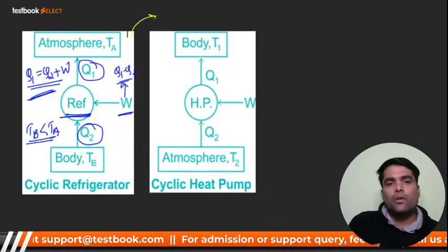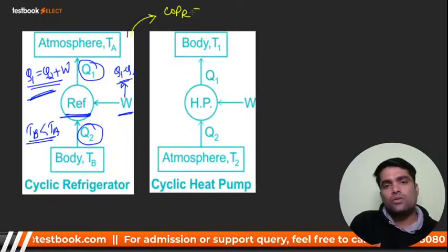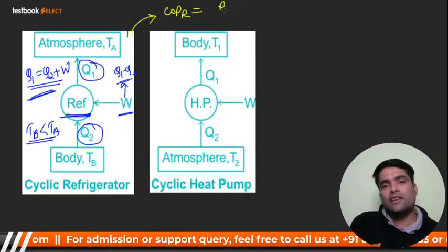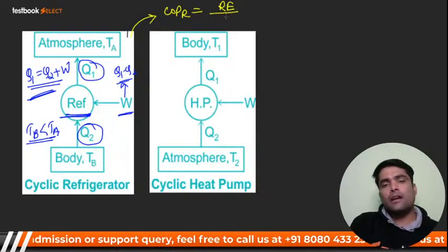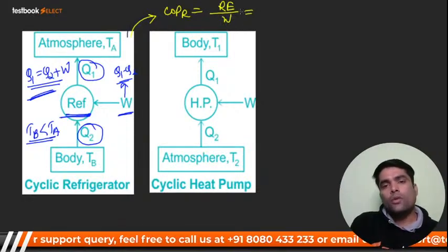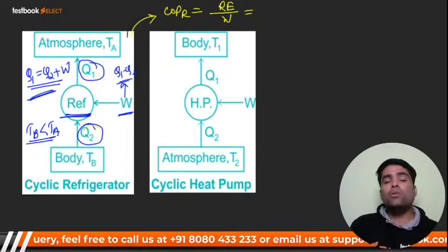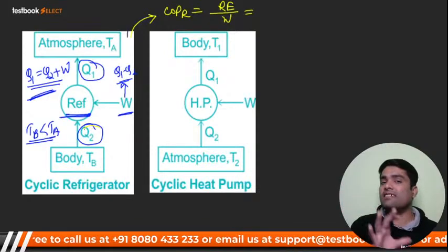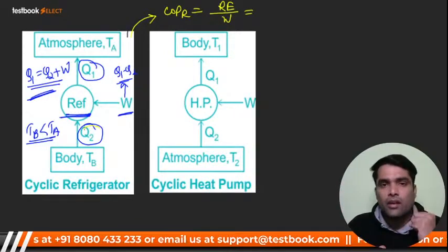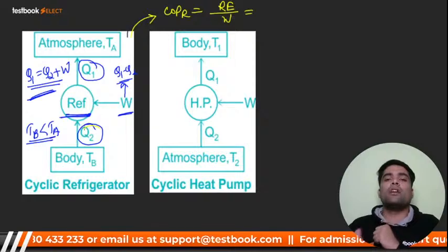What is COP for refrigerator? Right. So COP of refrigerator, that is desired effect, that is refrigeration effect, divided by W. So what is the refrigeration effect over here? The amount of heat that you remove from the conditioned space, जो भी space से आप जितना amount of heat remove करेंगे, that is nothing but your refrigeration effect.